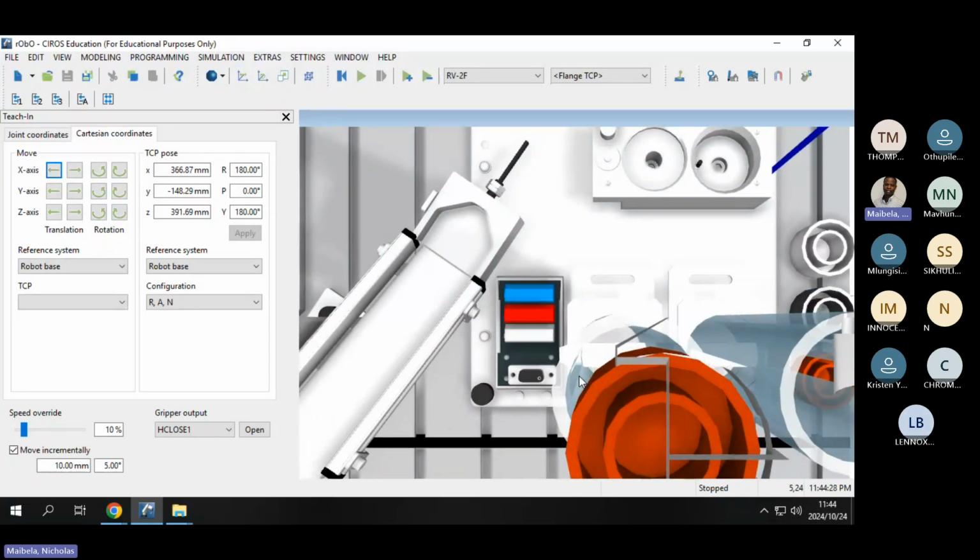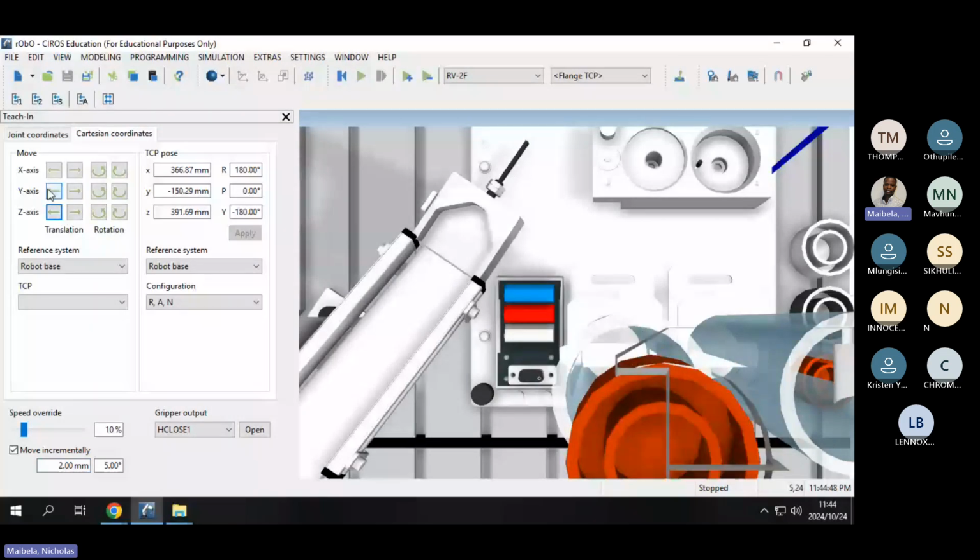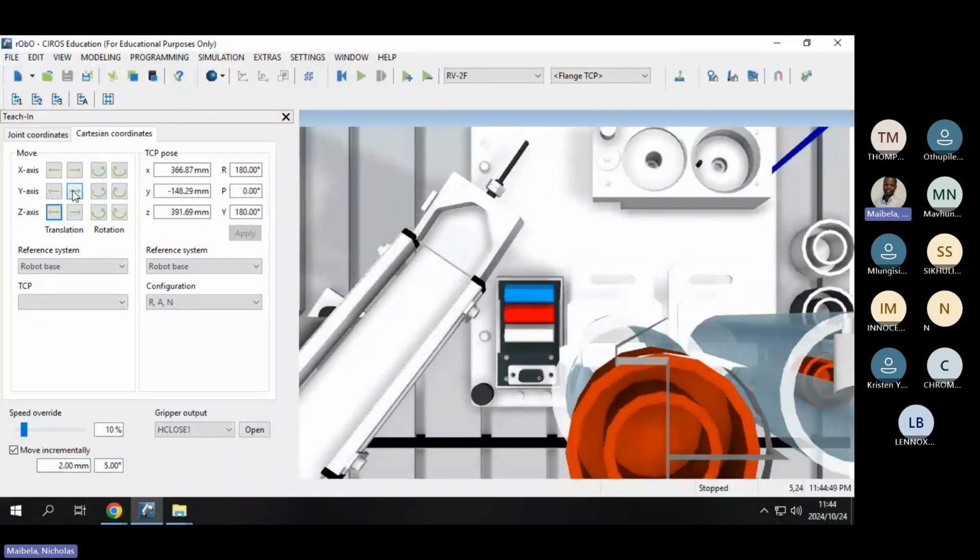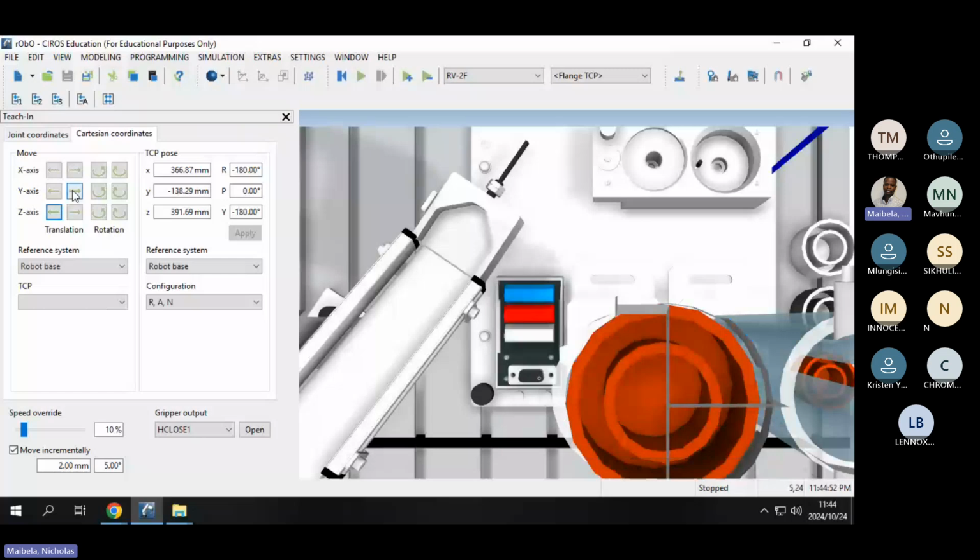We are located more or less accurately above your cylindrical magazine, but we're short by this space. So you can also decrease the move increment to maybe 2, and then take it, not down, take it to close that space there, that gap, like that.